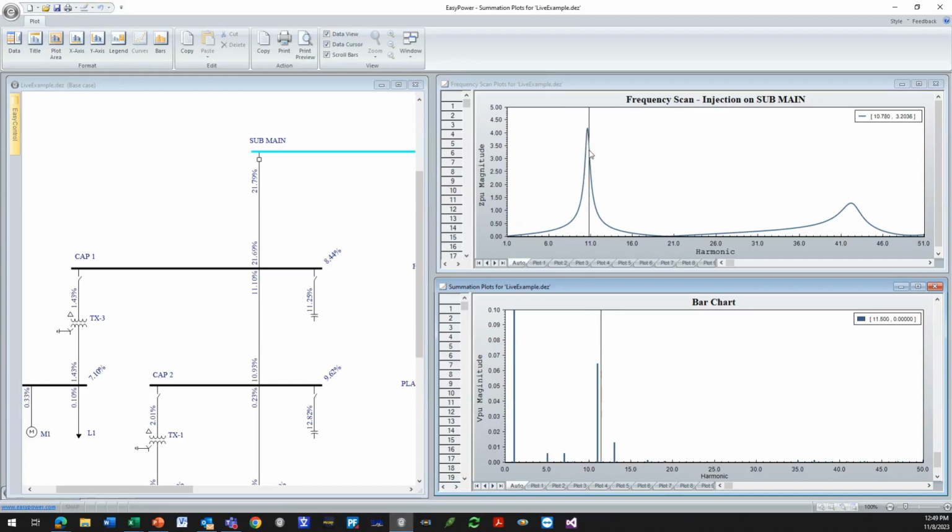So you can see that this location, somewhere around the 11th, corresponds to right here. Now, notice at the 11th, it's on the right side of the peak, and the 13th is still amplified a little because it's on the slope over here. It's still on a bit of the amplified slope. Okay, so the resonant point transfers to actual distortion amplification, and we see the results displayed as THD right on the one line.